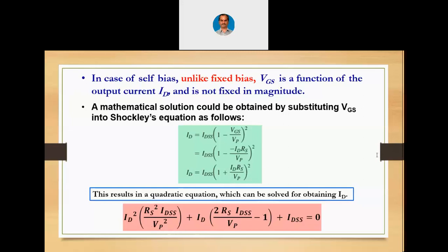Now we have to turn it off. For turning it off, we have to apply negative potential to the gate. So if you do not understand this, you will have to refer to the previous class videos again. That's all. Otherwise, I will keep on telling the same answer again and again. That JFET is normally on. We have to turn it half off by applying negative gate bias. Because we apply negative gate bias, JFET cannot have a gate current at all. This I had discussed in the earlier classes. If you had been absent for some of the classes, you will have to refer to those videos. Now let me continue the discussion.